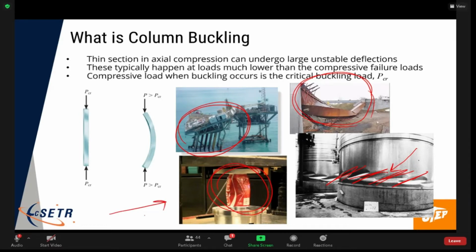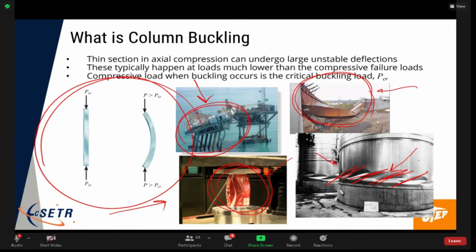These are all types of buckling. And what we're going to talk about is basically column buckling, which actually can be extended to a lot of these cases. This case, and even to a degree these cases, the first mode of buckling is a compressive load that we can treat with this column buckling model, okay? So that's the critical thing.